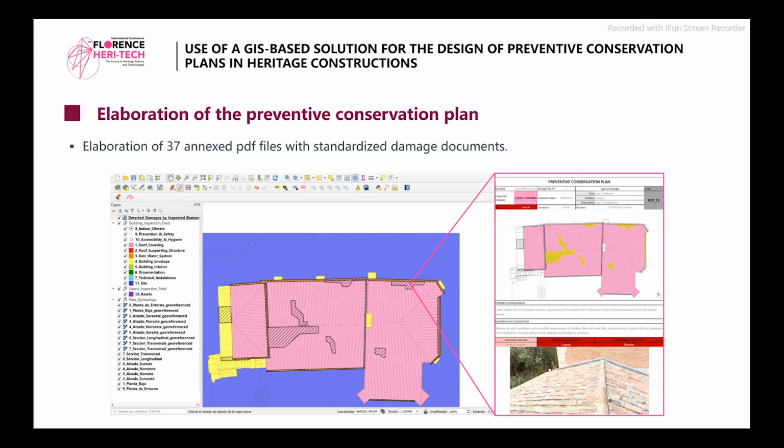Among the previous risk results and the damages files obtained, it is observed that the critical situations are caused by losses of material due to humidity and filtrations, damages which can originate biological colonizations, like the ones which appeared in the sacristy walls, with the growth of algae. To solve it, a daily or weekly ventilation and control is recommended, realized by the church owner.